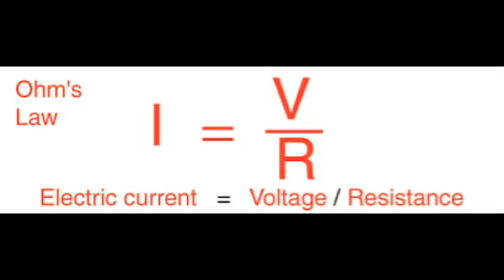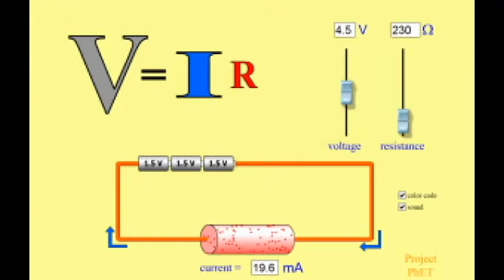Thus, the equation R equals V over I, where R is the resistance, V is the potential difference, and I is the current. Or the equation that we're going to be using, and that is the most effective one, which is the same as the other one, just written in different terms, is V, the potential difference, equals I times R, the current times the resistance. This equation is also known as Ohm's law, which is just a description of a certain class of materials. The unit for resistance is called the ohm, abbreviated by the capital letter omega, and it is equal to 1 volt per ampere.